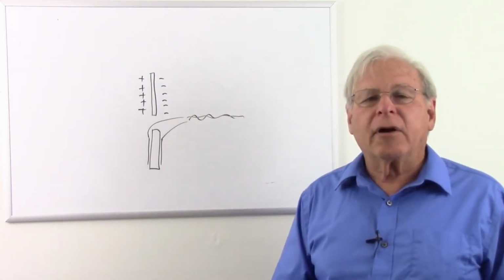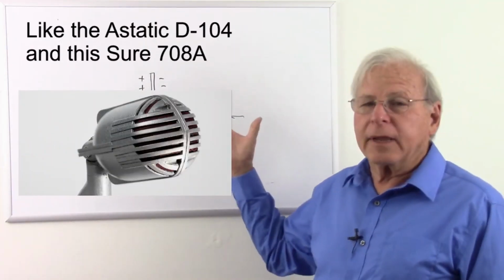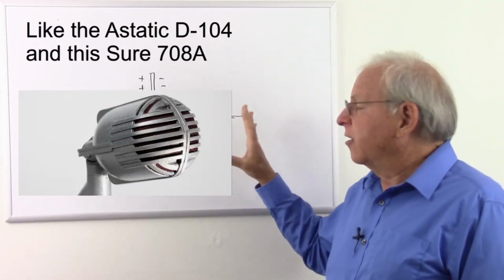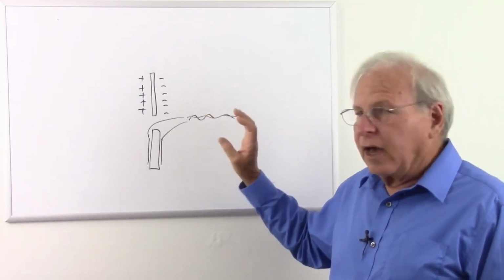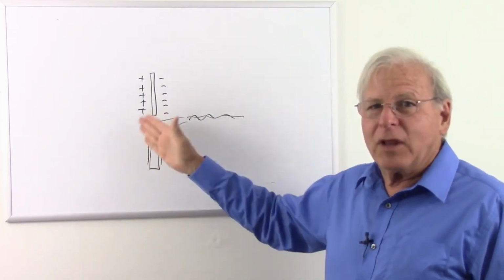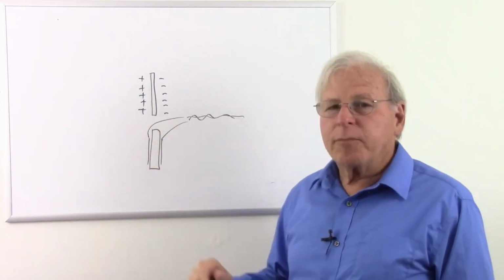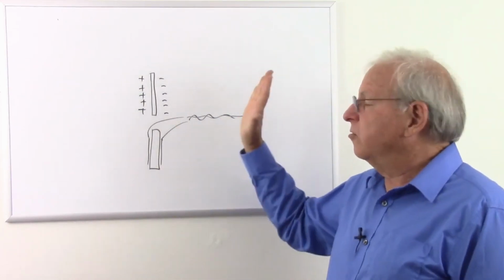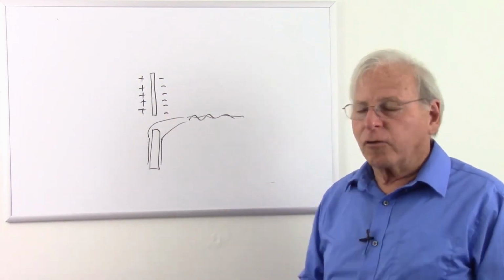And there are also high quality crystal microphones used in sound production. Not as common as dynamic microphones or ribbon microphones, but they do exist. Obviously, they have a very high impedance because there's no electrical connection between the two plates. But that's one property of piezoelectricity. One, you distort it, you get a voltage. If you put a voltage across it, it distorts the crystal.